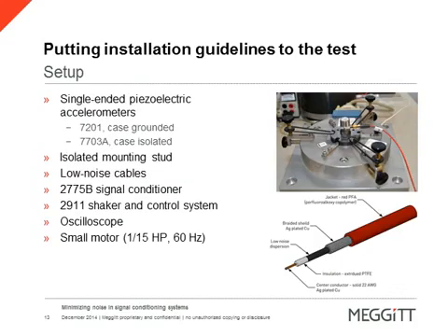Thank you, Tim. Good day to all our attendees. I'm going to transition this presentation into some applicable testing that we perform to try to validate this information that's presented. This slide is talking about the setup. We have a single-ended piezoelectric accelerometer, two types, a 7201, which was case-grounded, and a 7703A, which is case-isolated. Both of these are single-ended piezoelectric accelerometers, so they have a high impedance charge output.